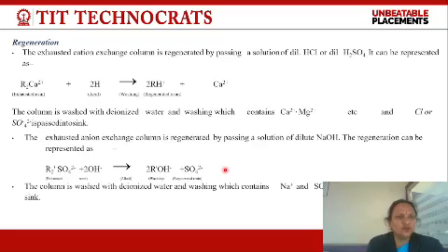In the zeolite method, it works on the cation exchanger process, and when we pass water through the zeolite exchanger, sodium ions exchange all the calcium and magnesium ions, and after the process, we get sodium ions with the water. In the ion exchange method,